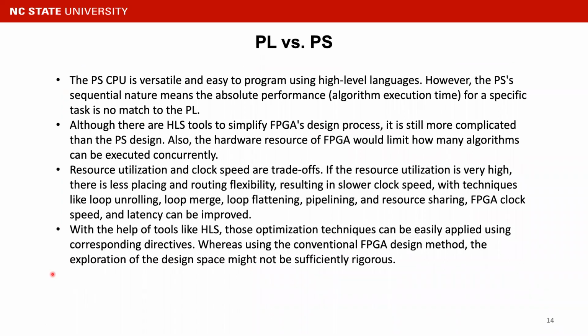As we mentioned, here's a comparison between the PL and PS. The PS CPU is versatile and easy to program using a high-level language. However, the PS's sequential nature means the absolute performance, i.e. the algorithm execution time for a specific task, is no match for the PL. Although there are high-level synthesis tools to simplify the FPGA design process, it is still more complicated than the PS design.